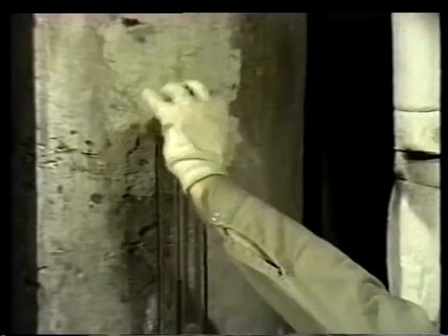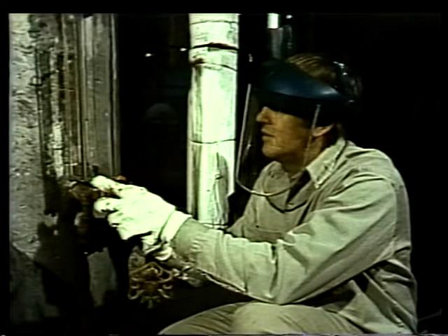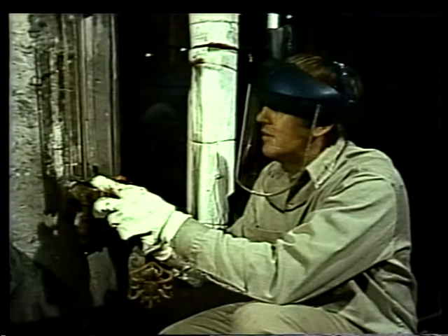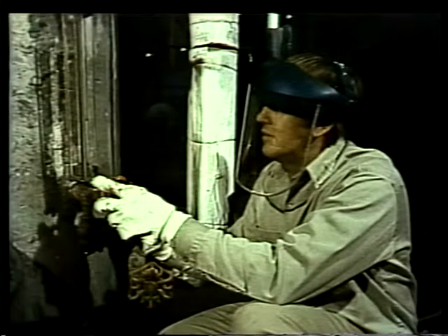When a gauge is returned to service, it is put under pressure. If you work on a high-pressure gauge, you must wear full face protection and gloves when returning the gauge to service. They will protect you in case the gauge leaks or the glass blows out.